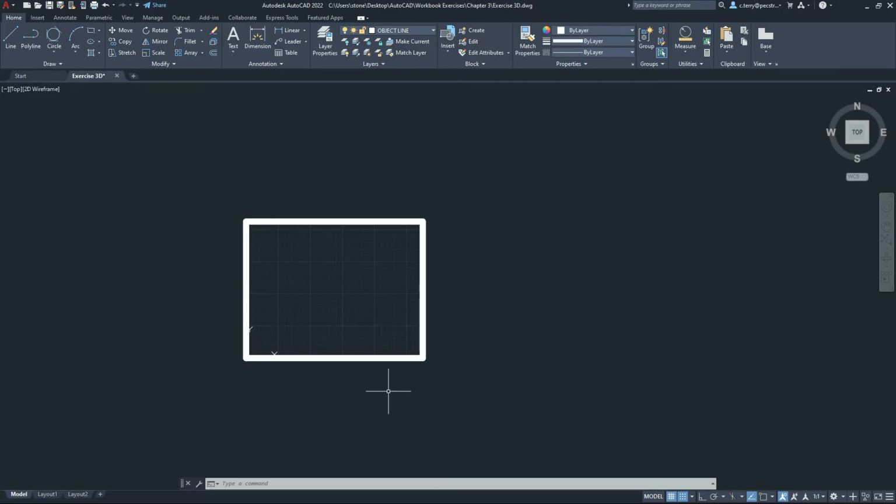Draw the objects below using the following layers: roof, wall, window, door, and plants. You can change the snap and grid settings to whatever you like. You decide when to turn ortho snap on or off, and all objects must be placed accurately. All lines must intersect exactly. So let's draw the roof first.